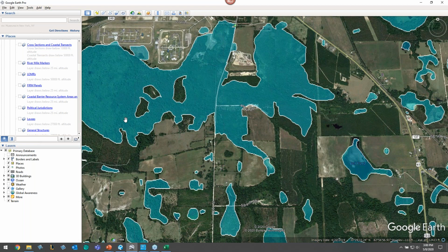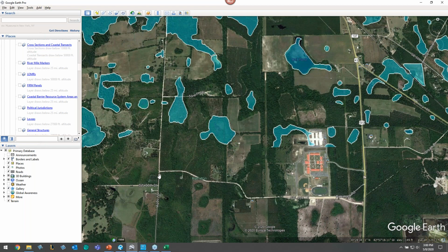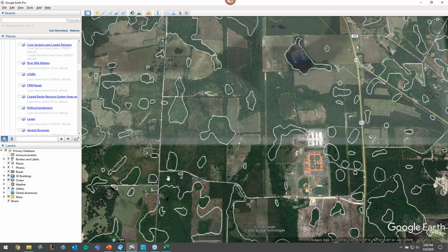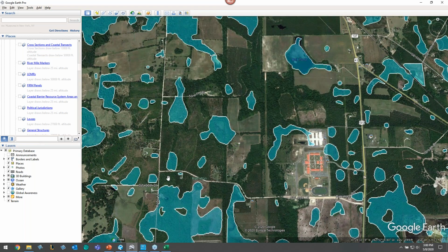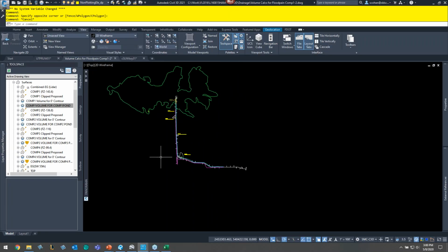That's the first thing. Now, as far as getting the shape, it depends. FEMA does allow you to download some shapes, but they get really, really big. So you can use Map 3D to bring them in. Or what I find works a little better, and I think that's what I did with this one, this is just Hamilton County, so it's a little smaller. Basically, I use the map import functionality, because once I downloaded the shapefile, I could then import it. That seems to work better. You actually get CAD graphics, and then I can do stuff with it. So that's basically what I would do.